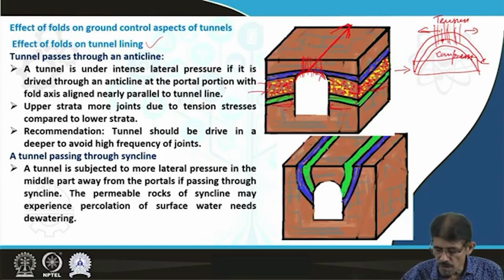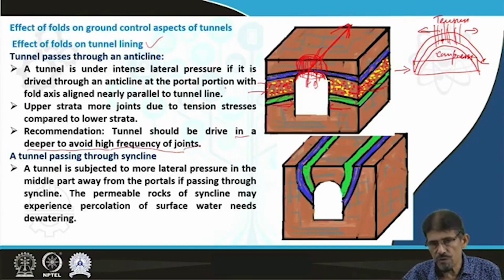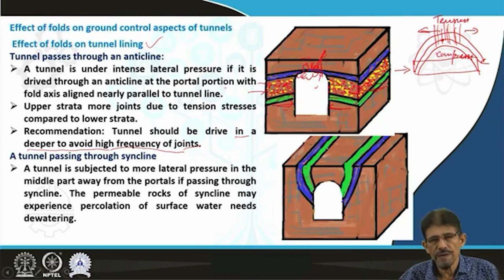Then there is a problem of flow of surface water as well as fall out of this zone. So therefore the tunnel should be driven deeper to avoid high frequency of joint, and the problem of rock fall and water drainage can be minimized in this way.